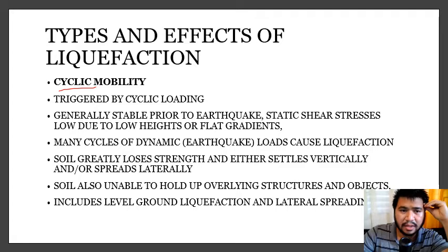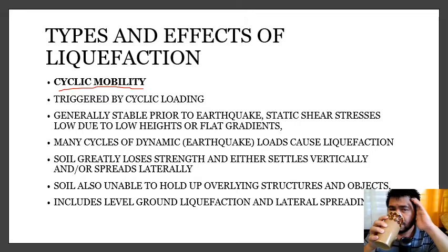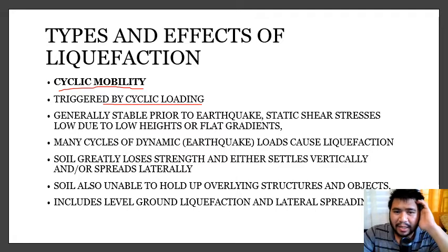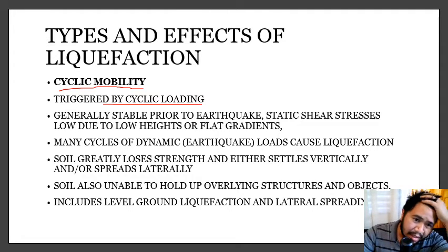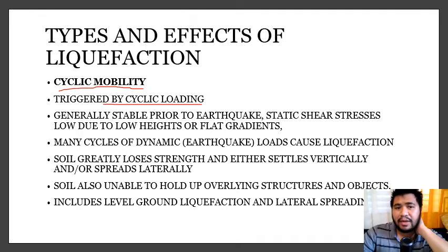And the other type is your cyclic mobility. This one is more triggered by the cyclic loading, in contrast with the flow liquefaction where the trigger is just a few cycles of seismic loading. In here, the ground actually experiences a lot of cycles of dynamic loading.